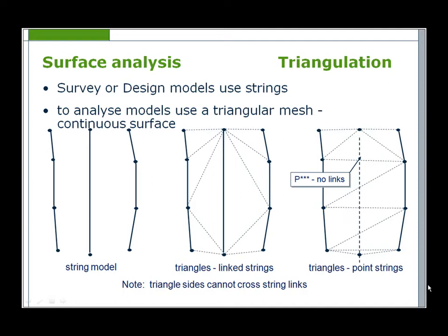To resolve that particular problem, you will have to change the name of the string running down the middle of the road to any other string name other than P, because a string name of any other than P will create a link between the points.